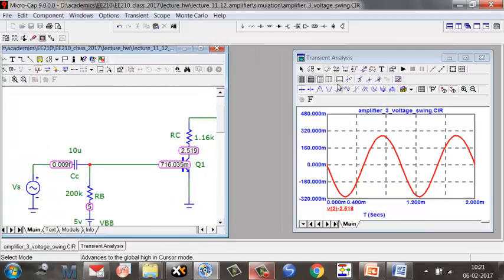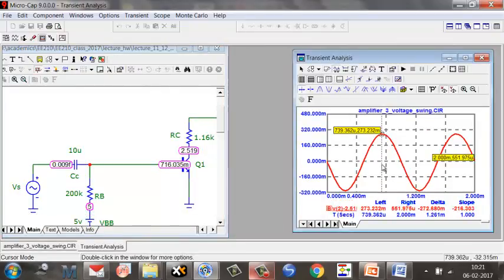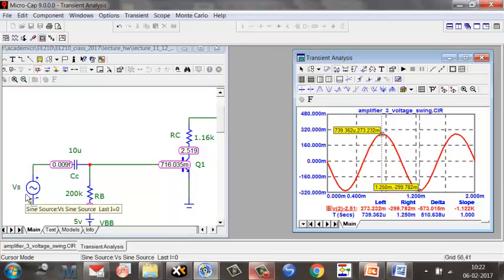All right. So, well, we get lower swing. Why? Because I've applied a lower voltage here. So to get a higher swing, you'll have to drive a larger value of input voltage also. If the swing has fallen for the same input voltage, it's because we have smaller gain. Okay, so that was expected.